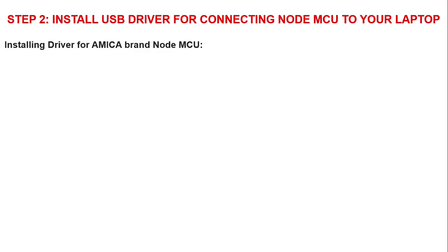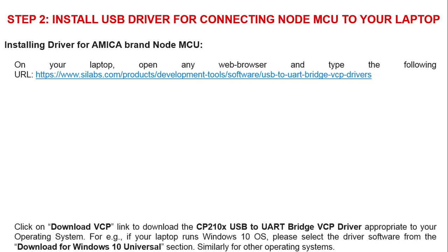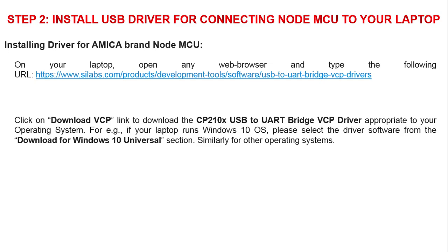We have to install a USB driver to connect the NodeMCU to your laptop. The installing steps are: on your laptop, open your web browser and type the following URL, as we have seen, and then download the CP210x USB to UART bridge VCP driver appropriate to your operating system.